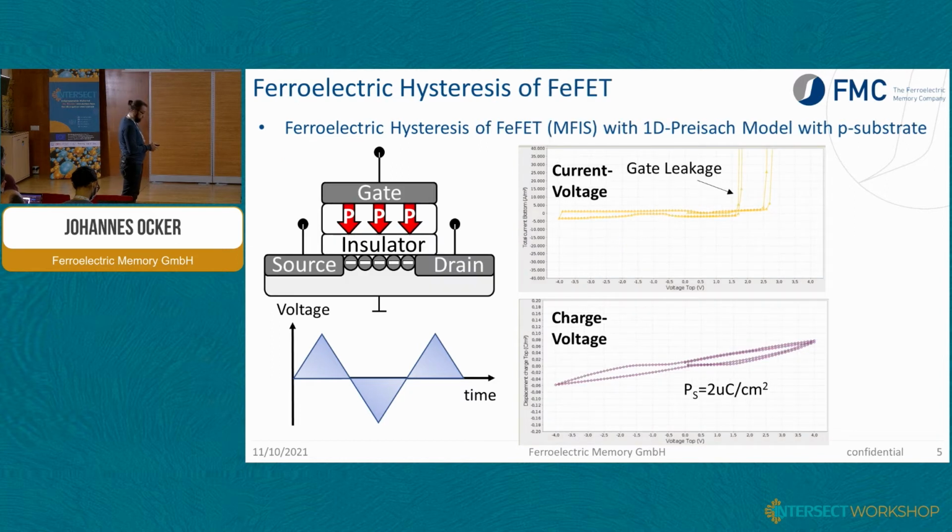So it looks like this. This is the same voltage applied, just we changed out the structure. We added here the silicon dioxide interface layer, and then we simulated also with the ferroelectric Preisach model the hysteresis. And so you can see here, I can maybe switch back and forth,